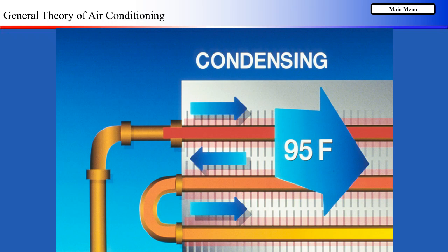Refrigerant in the outdoor coil condenses from a gas into a liquid at a fairly constant temperature. As the refrigerant flows back and forth through the coil, more and more of it condenses from a gas into a liquid until it becomes completely liquid. The latent heat required to condense this gas is rejected from the refrigerant into the air, thus heating the air. In the refrigeration business, this process is called condensation. The coil where condensation takes place is called the condenser.